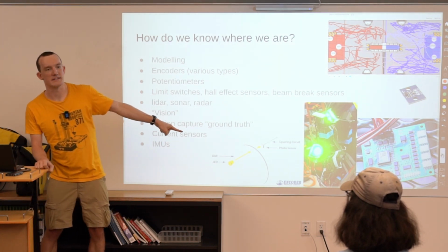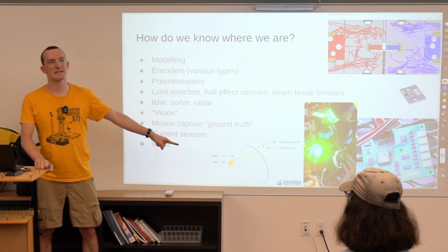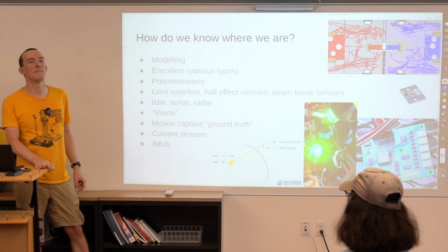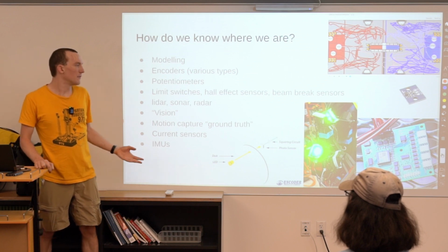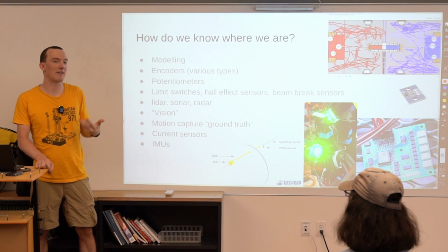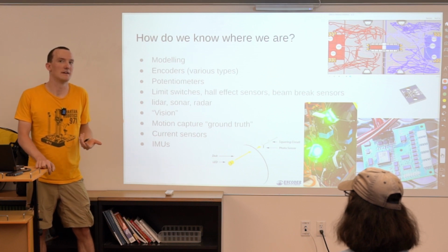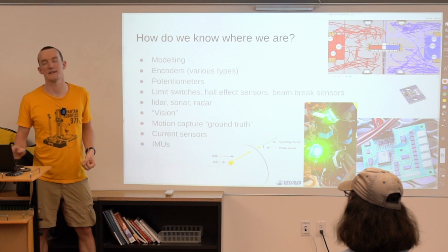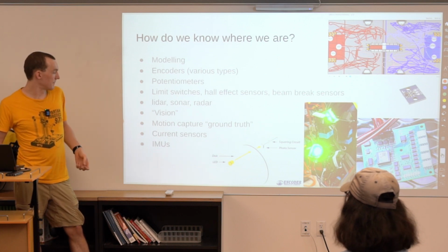Encoders don't measure velocity directly. They don't measure how fast something is spinning. They measure the number of cuts they counted. And so if you're trying to control the velocity of something, you need to understand exactly what it is you are measuring and what it is you are going to end up controlling if you try to use a certain measurement directly or indirectly.